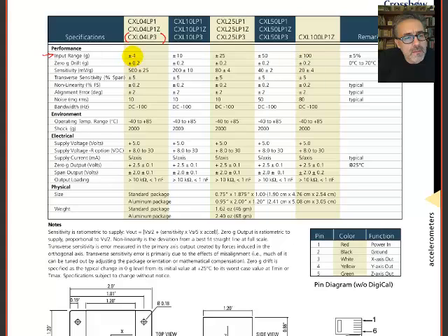But note that the input range is plus and minus 4, and then the units G. In other words, the devices in this column can handle acceleration inputs of plus or minus 4 Gs. Note 10, 25, 50. So up here you're getting into some high performance accelerometers. What that means is, the more acceleration they can handle, the less sensitive they're going to be. In other words, the output's not going to be as high, but they're also going to be stiffer.